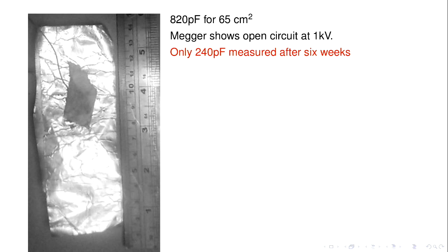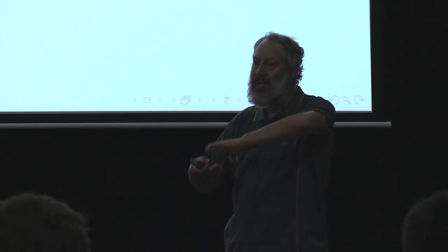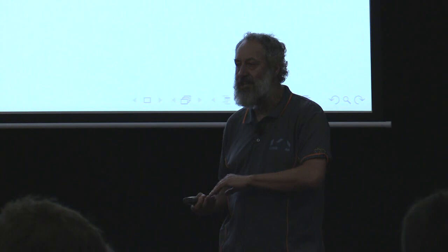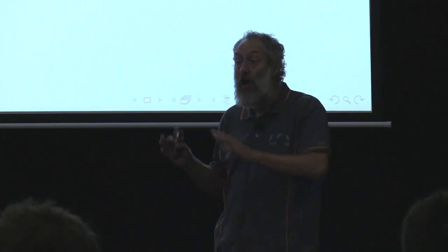And then I measured it last night, and it was like 100 picofarads. Something's going wrong with my capacitor. My guess, and I don't know this yet, is that some of the capacitance that I measured when I first measured it was from the dielectric in the glue, not in the plastic. And as the glue settles and dries up over time, the capacitance changes. That's my guess. I don't know for sure.